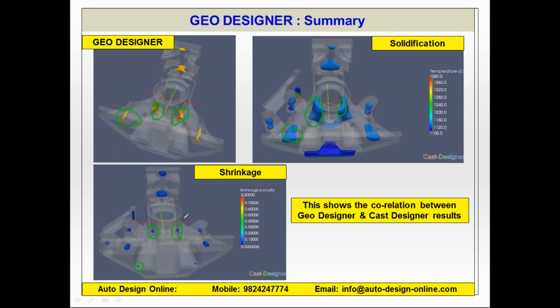So why I was saying earlier is that this can even save the time of the simulation. You can see here now that even without simulation, what we are predicting is 100% correct. We are not presuming or assuming anything which could be different in the solidification pattern, right? So what you can see justifies the location where hotspot or shrinkage is likely, and accordingly you should think and try different gating system designs to overcome this problem later on, right?